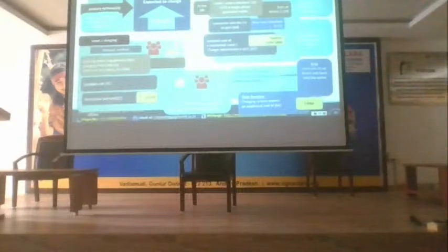select how much sufficient time you have to charge your vehicle, and how much time you want to run your vehicle once it is completely charged. Based upon all these things you need to select, right? So if you are at home, meaning you are a residential customer, you have level 1 only. In level 1, there are varieties of power ratings, like 10 ampere charger, 20 ampere charger. It depends upon how much time you want to charge.